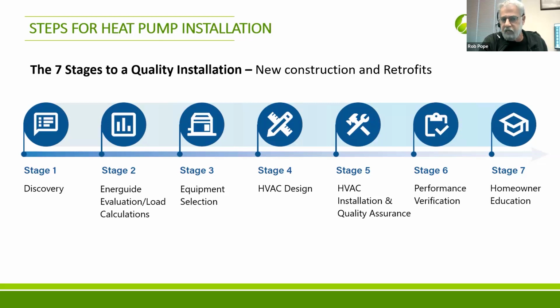But if the house gets tight, if that building envelope doesn't leak that much, and the only way you can know is a blower door test. So, if you test at, say, 5 air changes per hour or less, then an HRV is a really good idea. You should put it in. If you're at 3.5 air changes or less, then you absolutely need to consider an HRV. Otherwise, it'll get stale and stuffy in there. It won't be good air quality in the house. Sorry, I mean HRV, yeah.